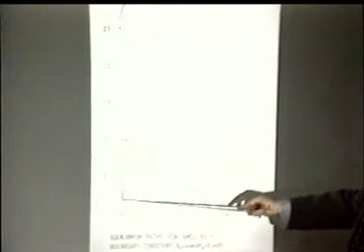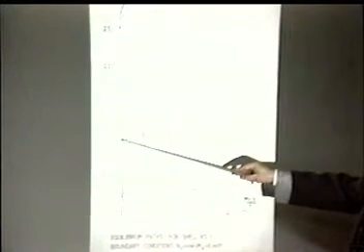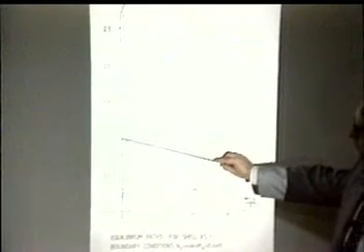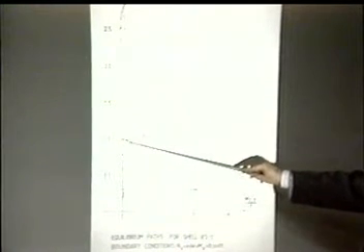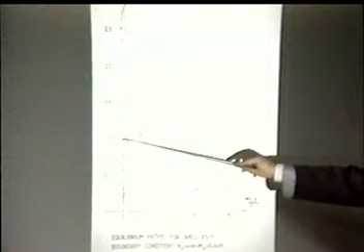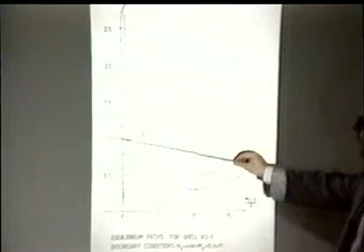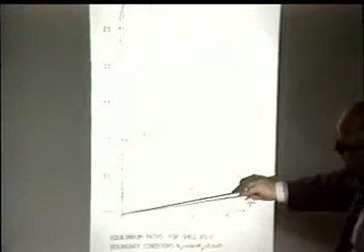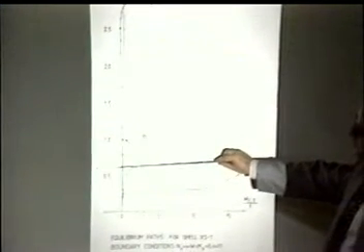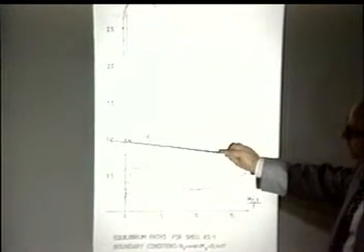For instance, what you have here is a pre-buckling curve. The perfect shell bifurcates there. Immediately after bifurcation, the slope of the post-buckling path is negative, so you expect it to be imperfection sensitive. And if you step over onto this branch and calculate it, you notice that the slope becomes more and more negative, and then it comes back again. So that if you put in an imperfection of the size of 1 wall thickness in the shape of the buckling mode, you get a 40% decrease in the load carrying capability.